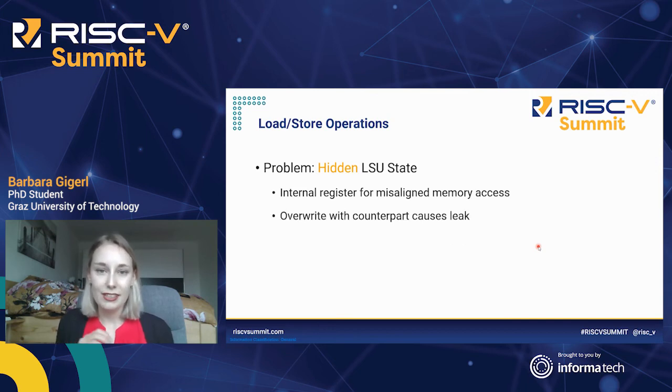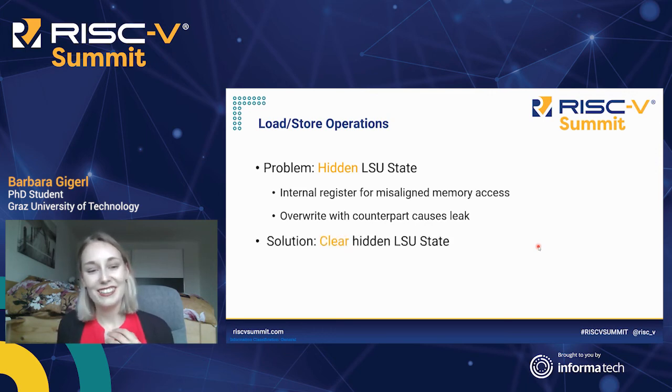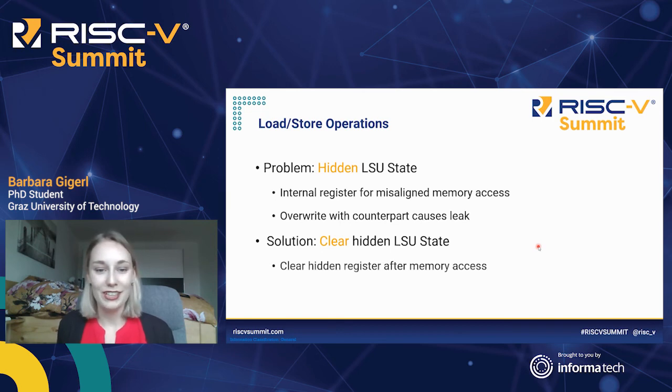And if this internal register contains a secret share and is overwritten by its counterpart, we have a leak. So thankfully, the misaligned memory accesses take quite some time, and we can just use the last cycle of this time frame to clear this register. So there's no overwrite anymore.